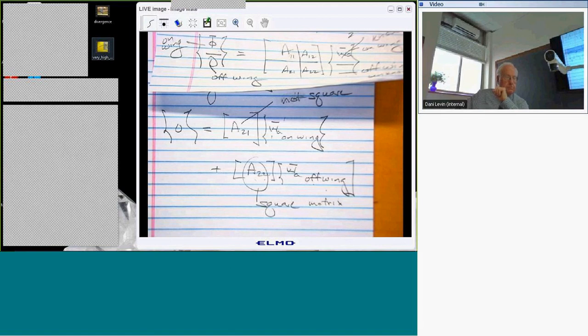Also, remember in our discussion, we were saying that the perturbation pressure for this case is 0 off the wing. And we said there's continuity, and therefore you would expect the perturbation pressure to be 0 right at the trailing edge, which is the interface between the wing and fluid off the wing, and that's what we like. There is a small problem.